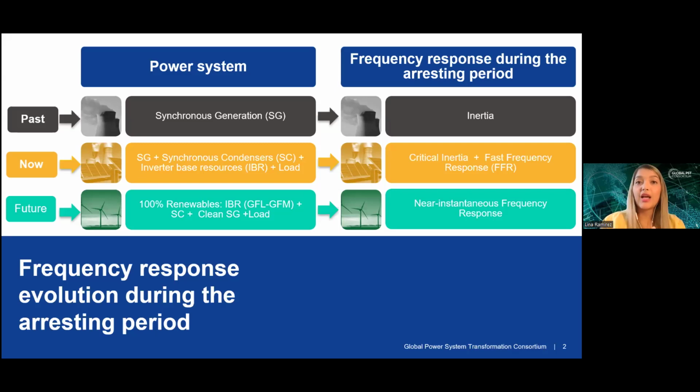And also, as we start to have more IBRs, we start to include other services from IBRs, so that we start to include fast frequency response that can help to reduce that critical inertia. So that is currently the things that are happening.